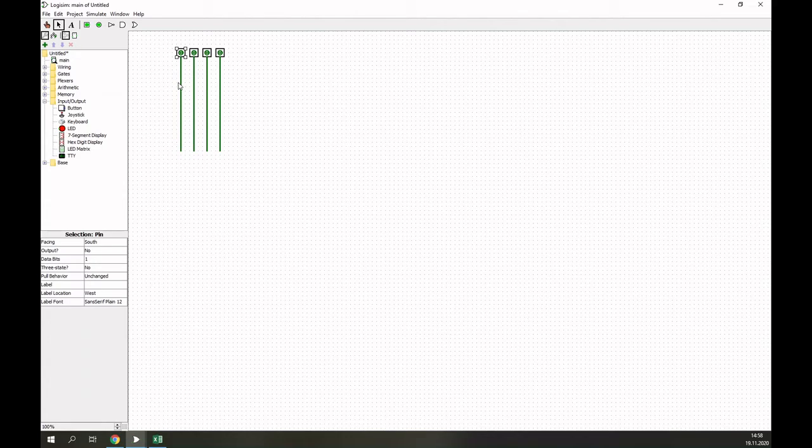And additionally, I have a selection line or a control word which selects according to the setting. So 0, 0 selects the first line, 1, 0 selects the second line, 0, 1 selects the third line, and 1, 1 the fourth line.